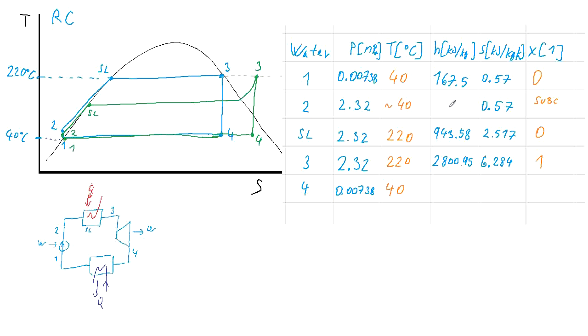If not, we could use, for example, steam density and pressure difference, while the pressure difference divided by density, or pressure difference times unit volume, would be the work of the pump, and enthalpy at 1 plus work of the pump would be quite precisely enthalpy at point 2.